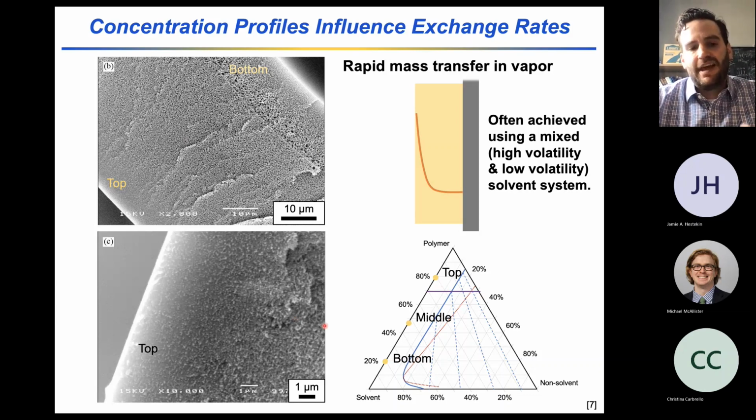And this is just a higher resolution SEM micrograph of this region of the polymer film, and you see that it is in fact dense and something that can execute a gas separation where you're trying to resolve molecules with fractions of angstroms difference in size.